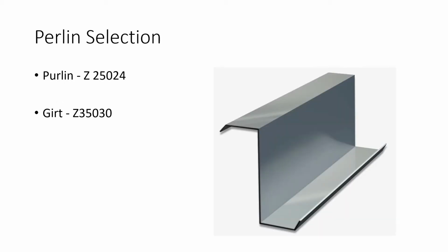Load calculations were calculated for purlin and girt line loads for each design member. The inward and outward loading was then checked against, leading us to choose a Z350-30 girt from the capacity table using a 6 meter span and 1 row bridging. The final step of member selection was to check if the size of the purlin was adequate. If not, a larger section would have to be chosen and rechecked. The member sizing was found to meet requirements and also be economical.